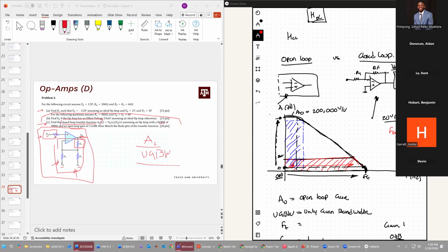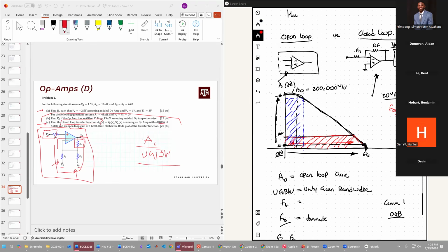So that's why in the problems, if you see a graph, or you see that the gain bandwidth product and the open loop gain are these values, that should tell you that someone has given you a device and a spec sheet and is saying, we're going to operate at a particular point on this op amp. What are going to be the characteristics if we operate at that point? That's the reason why you can't assume it's ideal, because this graph is literally characterized by the manufacturers of the op amp. It describes physically how well it operates at different frequencies and different gains.